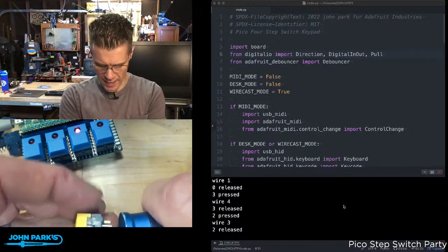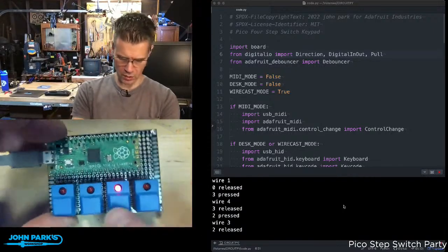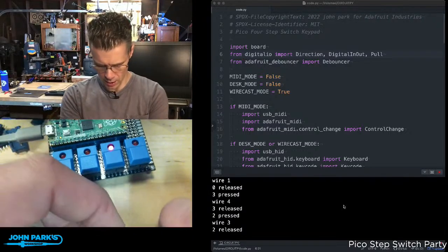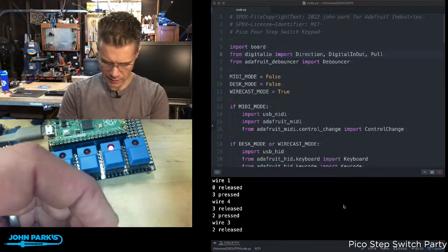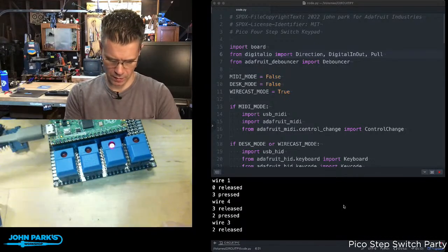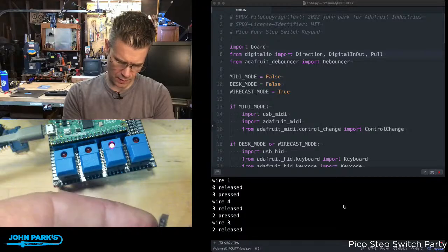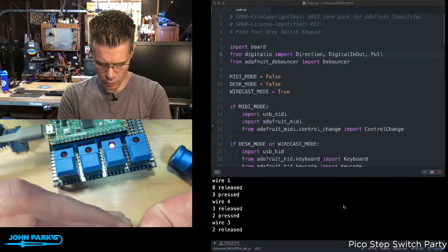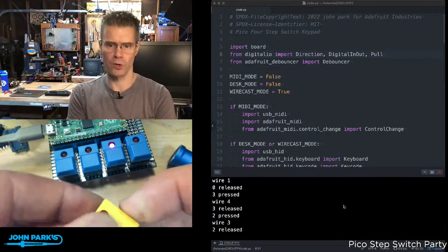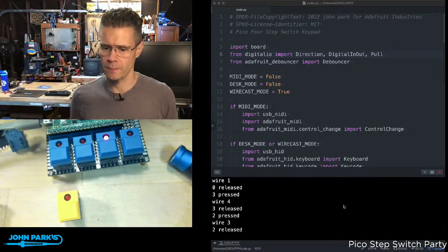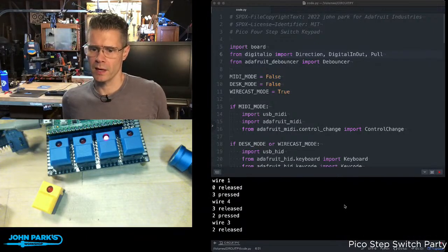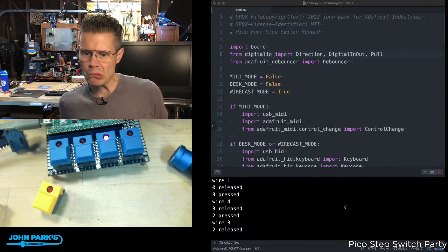You probably also choose your height. I didn't do this when I assembled this board, and I noticed some of these are slightly different heights than each other, so you could go in here, maybe lay something across the top like that, and start with it a little bit proud and press it down, or whatever you want. Get that to a consistent height before you go soldering it down, because then you won't be able to... Yeah, so no disassembly required to get the LED out, which is cool. Let's see, other questions? No?